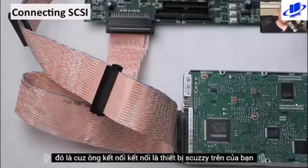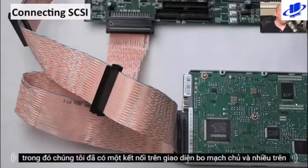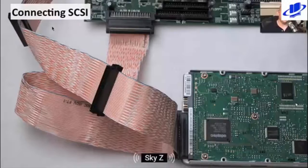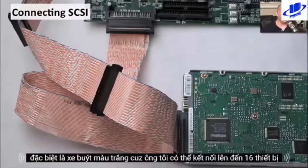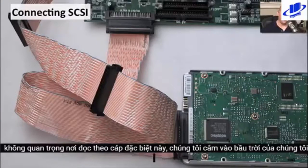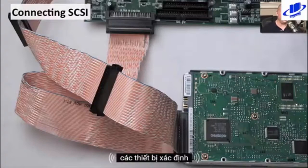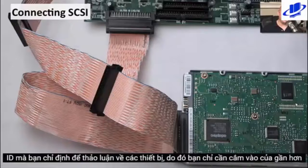The connection of the SCSI device on your motherboard looks very similar to PATA in that we've got a connection on the motherboard and multiple interfaces on SCSI. But of course, with PATA, we are limited to 2 individual devices, whereas with SCSI, especially the wide bus SCSI, I can connect up to 16 devices, and you would simply find the closest connector to you and plug it in. It doesn't matter where along this particular cable we plug in our SCSI device. The determination of how this device communicates is associated with the ID that you assign to the SCSI device.